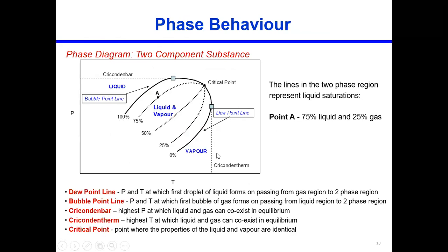We can find out from this chart what the current condition is, what the current pressure is, what the current temperature is. We can exactly find out the reservoir condition. Okay, further we can find out more, for example, how much oil is left or how much gas is there inside at this point. Okay, so this phase behavior diagram actually is an architect of the reservoir fluid in the reservoir.